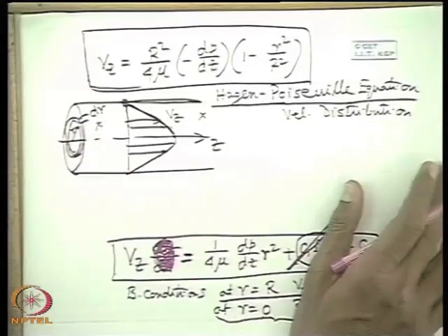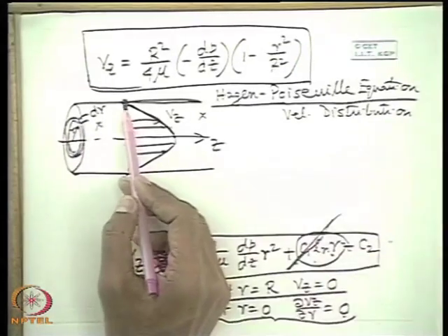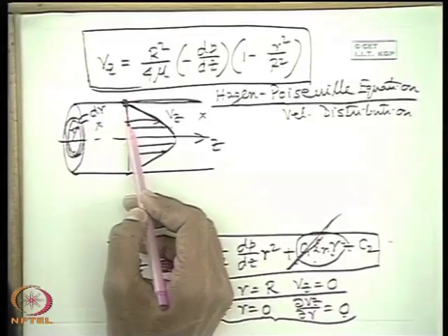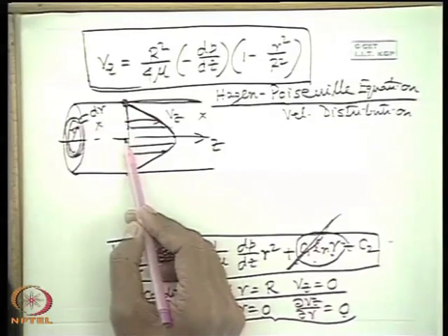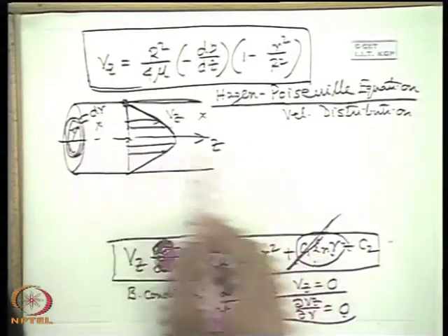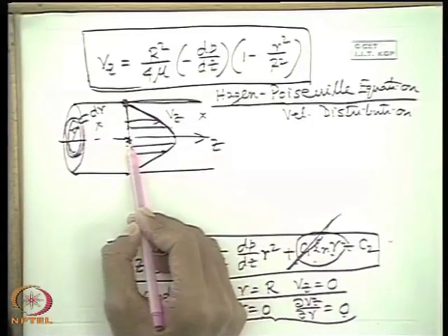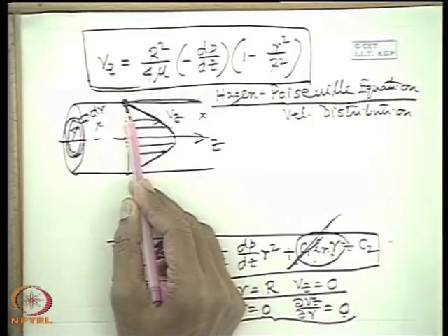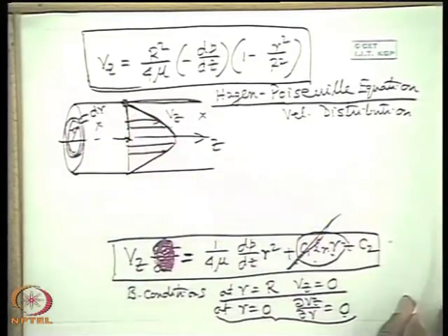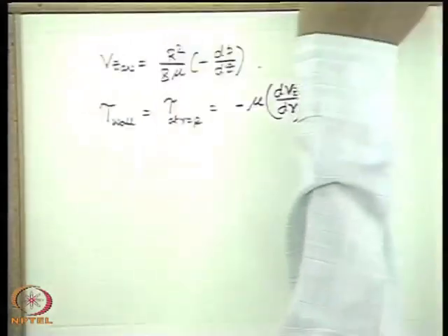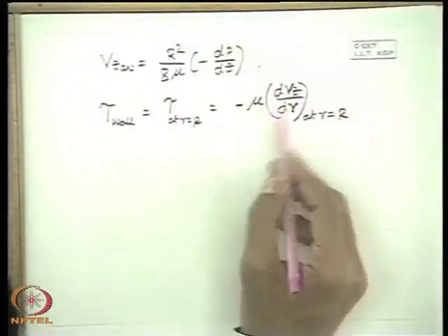We will see afterwards, we define a wall coordinate or normal coordinate from the wall, perpendicular to the wall along outwardly. But here in this conventional cylindrical coordinate, r is measured from the center. So an increasing r shows a decreasing velocity. To account for this, we conventionally put a minus sign in defining tau.